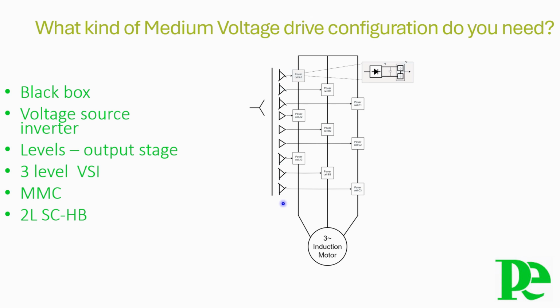provides for adaptability to available input voltage, and clean input power thanks to the cancellation of the harmonics by the phase displacement in the secondaries. Multi-pulse inputs go from 18 to 54. Isolation from the grid, avoiding potential resonances and reducing impact from utility transients such as lightning and other equipment switching.